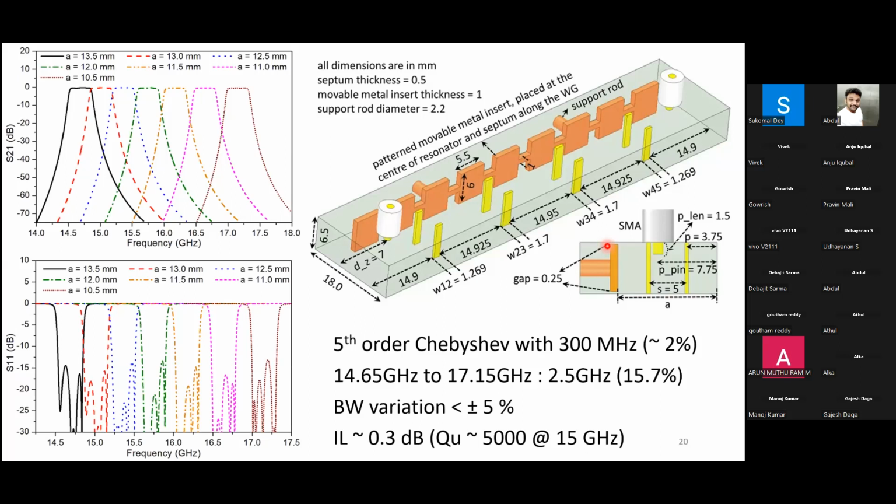It is possible to maintain a very precise air gap with an RF choke, which will ensure the air gap is maintained precisely and is very tolerant to vibration. So if we include an RF choke here, I would include a λ/4 resonator, short the λ/4 resonator, and then extend this path by λ/4 and short it. Then it is possible to make it robust to vibration. It's a very good question.